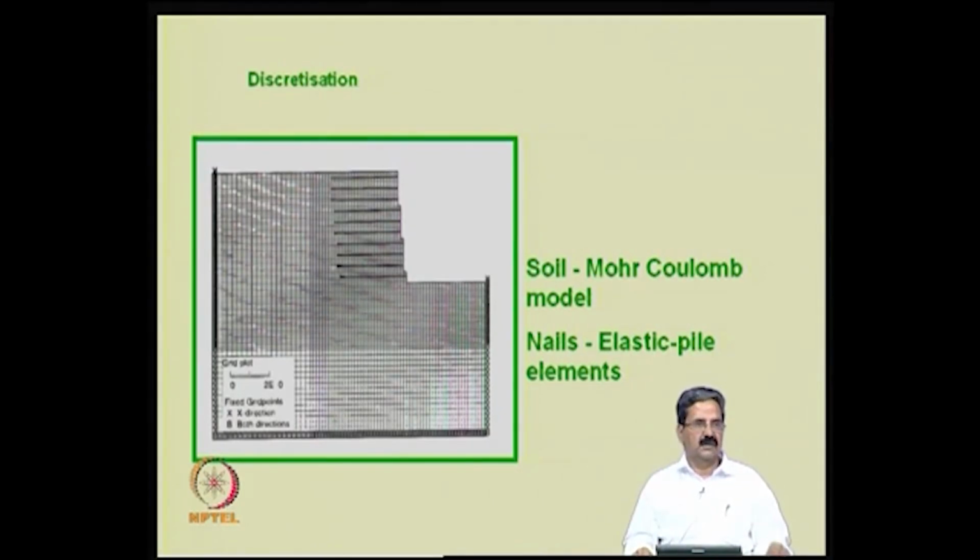How do you get that? T you should get, the tensile force in the reinforcement. How do you get it? It is nothing but the friction force around the reinforcement, 3.5 meters, and SV into SH. What is that frictional force? It is nothing but K naught into gamma h again, right. So, that is the earth pressure coming.